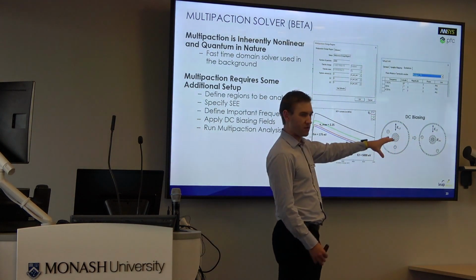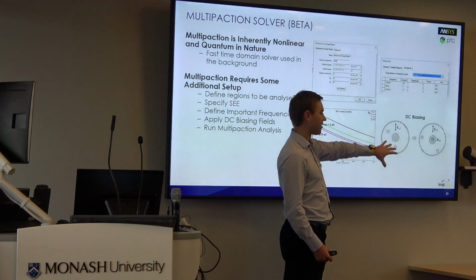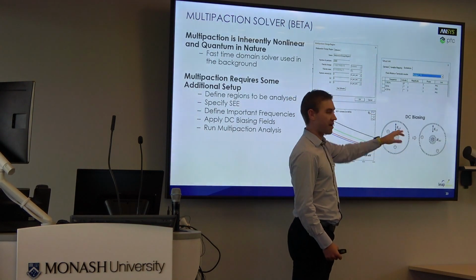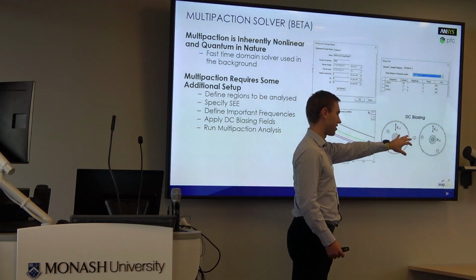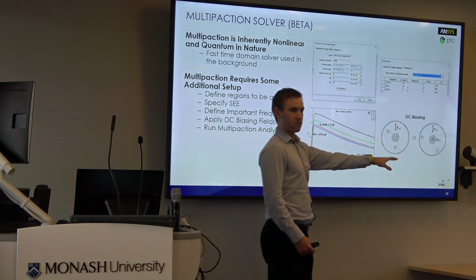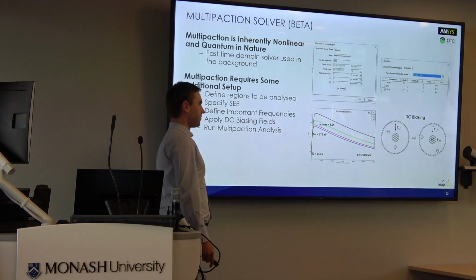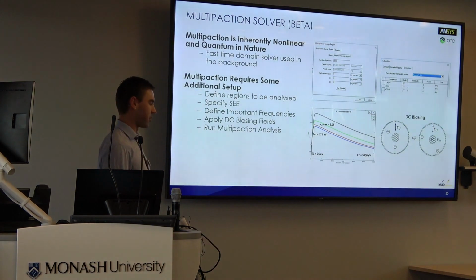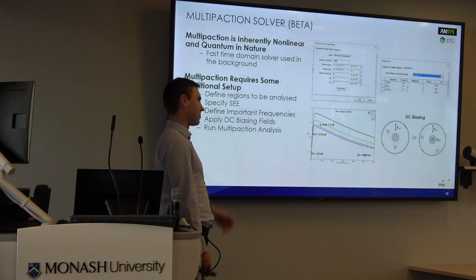If they have enough energy, which is usually when you have a very high-powered RF field, they can cause a cascade, and so this one electron will knock out more than one here, bounce back and forth, cascade, and produce an arc. The next part of the experience for your device will either be exploding, catching fire, or melting in some description.